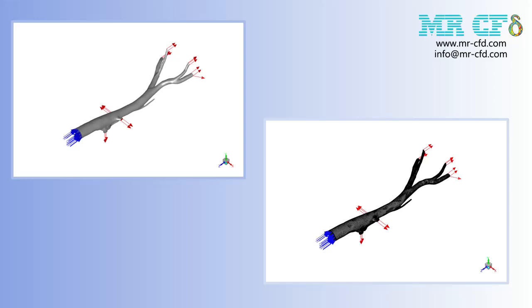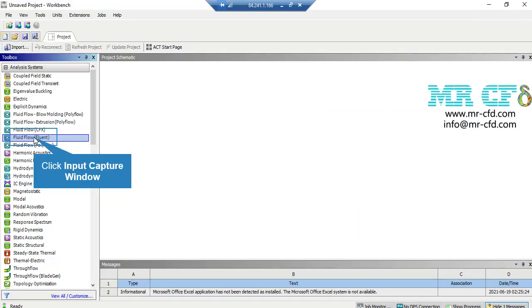First, the mesh was generated using the octree method and with 5 layers of prism mesh with a ratio of 1.2. Second, the Delaunay method has been used to improve the quality of the existing mesh. The final number of mesh cells is equal to 457,864.